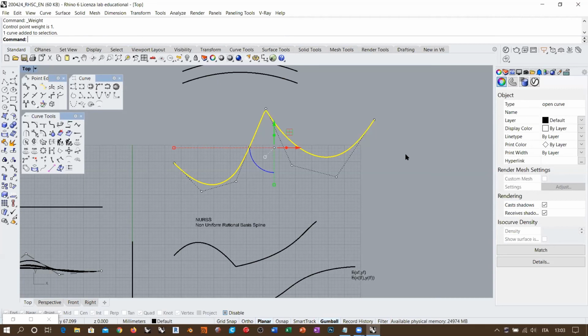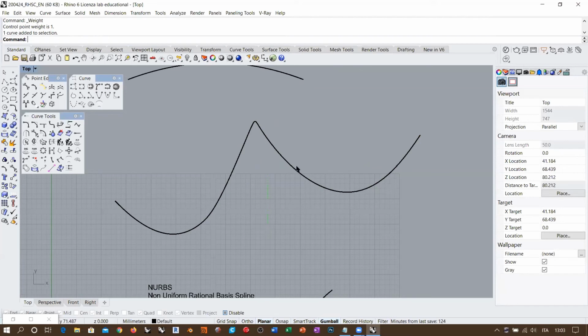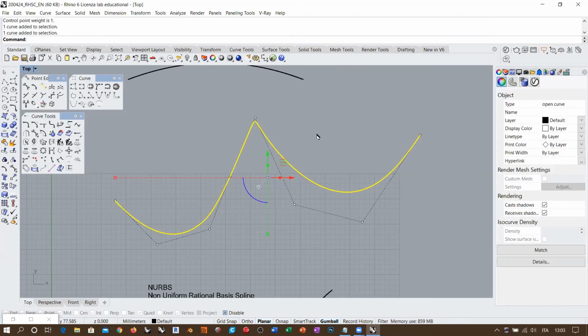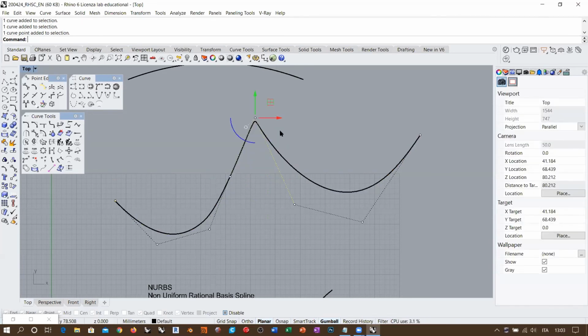But remember that this is a possibility that you can consider when creating your design. Because as you can see, for example, one thing that eventually you might want to do, instead of increasing the amount of control points to deform the shape of the curve in a particular spot, you might want to increase the weight of that control point that lies in that area in order to pull the curve stronger and create some kind of, let's say, more sharp behavior, right?